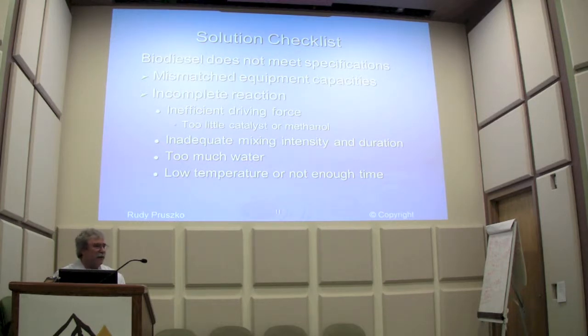You could, but then you have to heat it back up, so you're wasting energy. I'd plug the vent on the centrifuge, and it's usually a pretty quick process. Just realize you've lost some, and if you had excess before, it depends on how far your reaction went, you have to add a little excess anyway in the second batch to complete it. So I wouldn't worry about cooling it down.